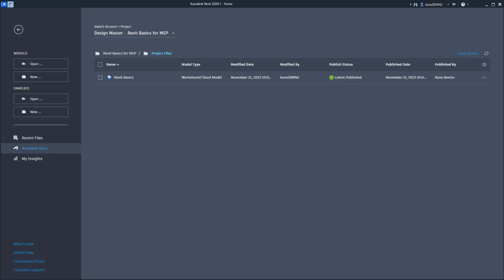Last thing to show related to worksets, which I alluded to before: when you open a Workshared project, you can choose to only open certain worksets. So if all of the MEP folks are in one model, but you just need your discipline, you can choose to not open the other disciplines to reduce your chances of accidentally messing with their stuff. If you have a very dense project, you can also choose to not load certain worksets to make Revit process faster.